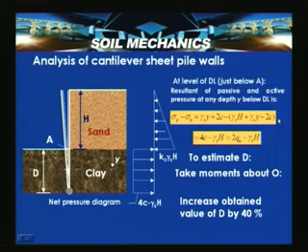So Ka is equal to 1 for phi equal to 0 soil, that is, this is the clay having phi equal to 0, so K is equal to 1. The factor is not taken because Ka is equal to 1 here, and Ka gamma_s h, gamma_c y, that is this portion, minus 2c. When we simplify, 4c minus gamma_s h yields 2q_u minus gamma_s h, where gamma_s is the unit weight of the sand.